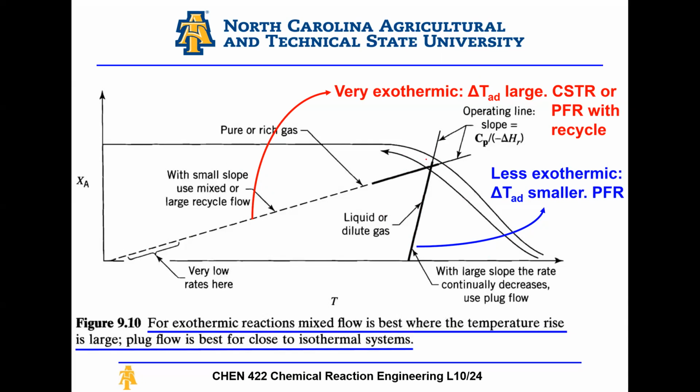Because when you operate with a CSTR or a PFR with recycle, you can really minimize your reactor volume, while having good control over this large temperature increase. You can always use strategies like purging, diluting, all this fancy stuff. But think about it, try to make the relations logically. The general idea: highly exothermic, use a CSTR or a PFR with recycle.